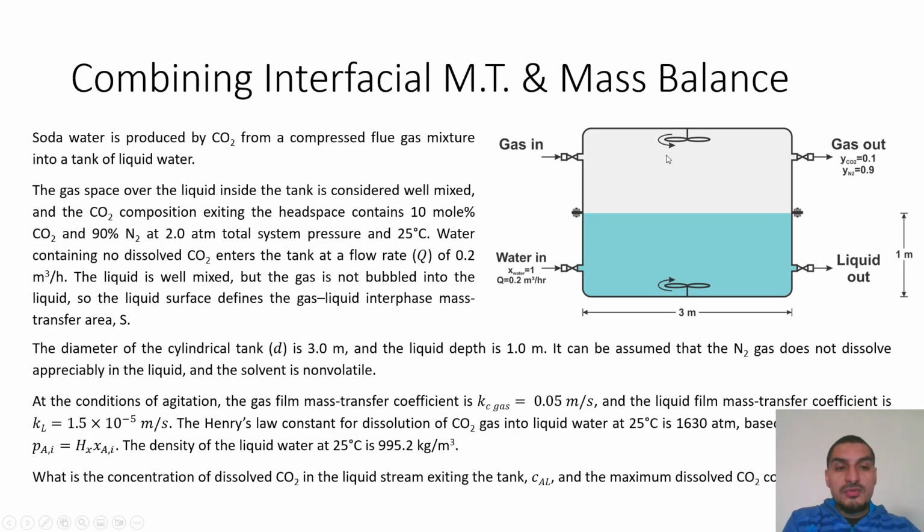So when you do perfect mixing, you assume that the concentration everywhere is, and that's why it's called perfect mixing, because you're mixing it perfectly so that the contents of the tank are homogeneous everywhere. So the concentration here and here and here and here are all the same. You have the same concentration everywhere, the same temperature, the same pressure. So it's exactly the same thing, because you are mixing this perfectly.